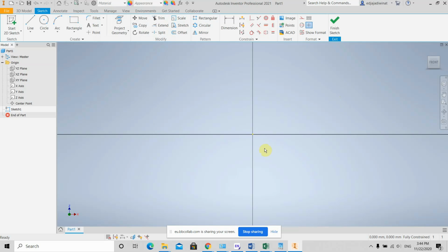Okay, we have entered the sketching mode. You can see this button. This means that you are inside the sketching mode. If you are done sketching, you need to click this finish sketch. Let's create the rectangle. I click the rectangle command, and I snap to the origin, the 0, 0. Make sure the snap to a point symbol appears, the arrow and red dot there. Then click.